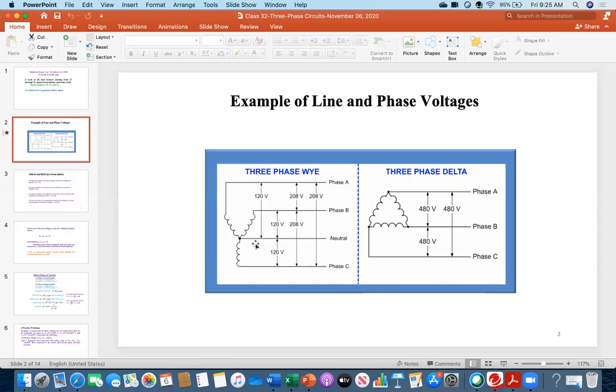The other thing is that, for example, the neutral current is flowing because of unbalance and it is going through the grounding, and you are standing nearby the grounding and you are barefooted. You don't have socks or you don't have any shoe. For example, you might get shock.